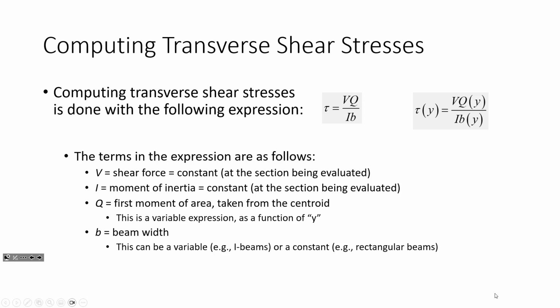And that's our, I know if you take mechanics of materials, the first, I'd say, 60% of the class is just focused on these 4 fundamental mechanical responses: axial load, bending, torsion, and transverse shear. Transverse shear is what we do last, and then we get into Mohr's circle and things like that. Now, in order to compute the stresses from transverse shear, you need 4 terms, okay?